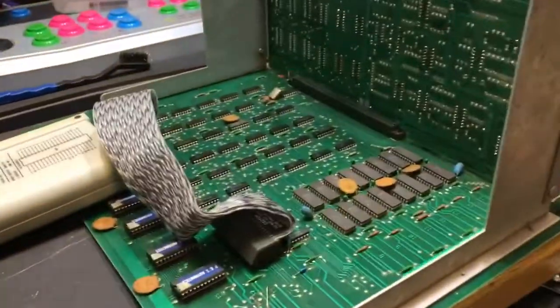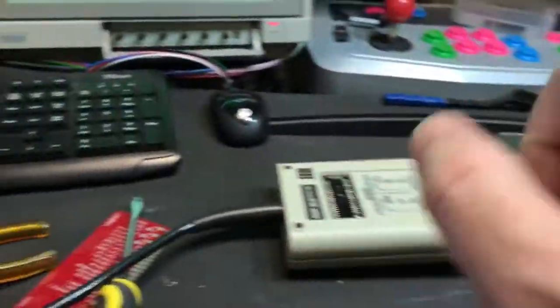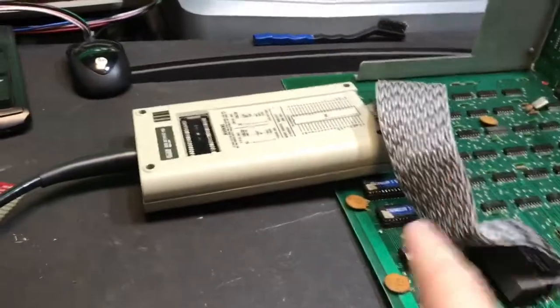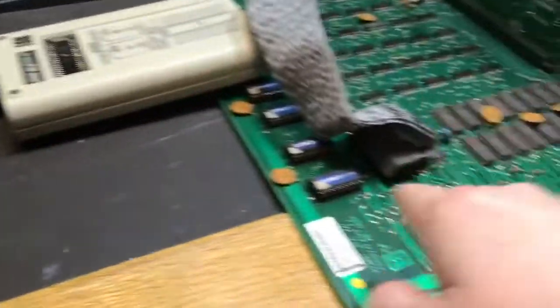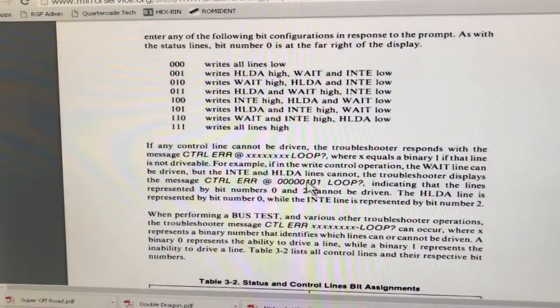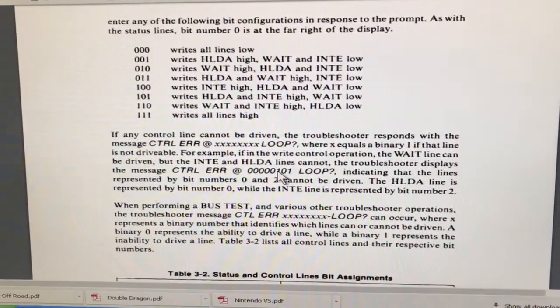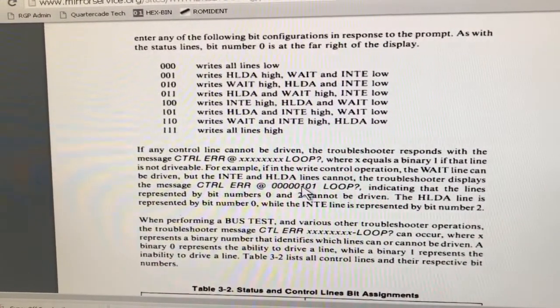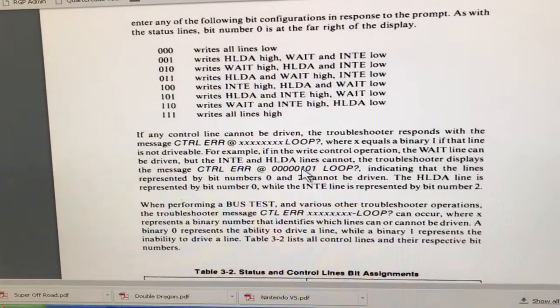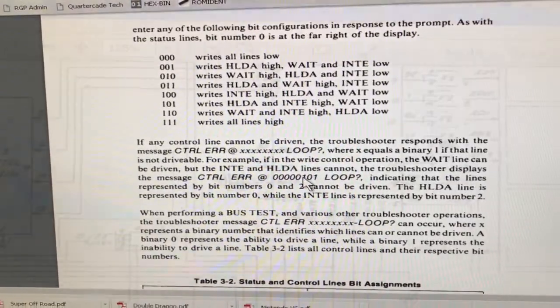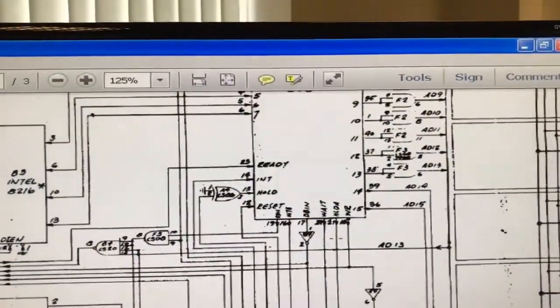Now, what I'll need to do now is get the schematic for the Midway boards, which is what this is, and find out where pin 16 goes to. So it sounds to me like there's a chip hanging off pin 16, which is stuck. Alright, so let's find that and clear that error, and hopefully, if we can clear that error, we can do a RAM write, and then we can run the program, because if that is sticking, I would imagine that that's half the problem. Right, now we're getting somewhere.